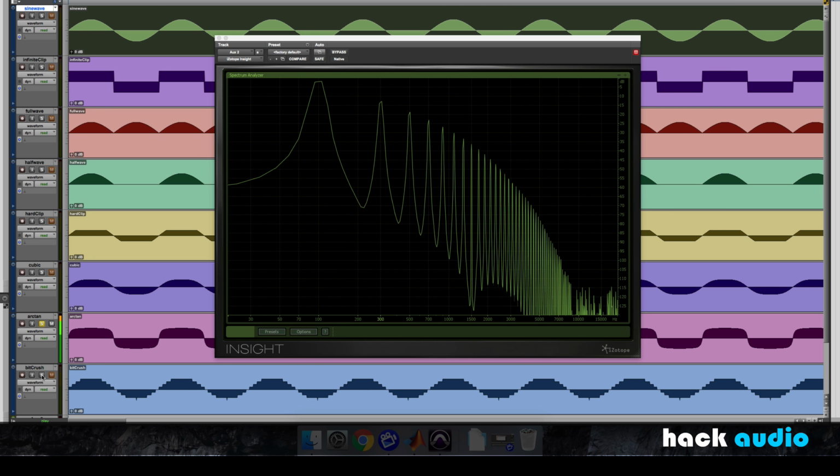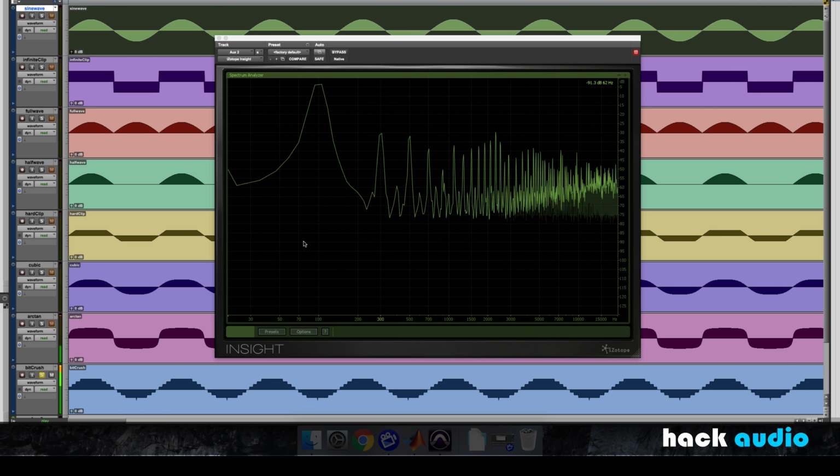Lastly, let's look over here at bit crushing. In this case, bit crushing is actually still going to be an odd function, where the positive amplitudes are similar to the negative amplitudes. So we primarily get our odd harmonics, 100, 300, 500, 700, and so on.